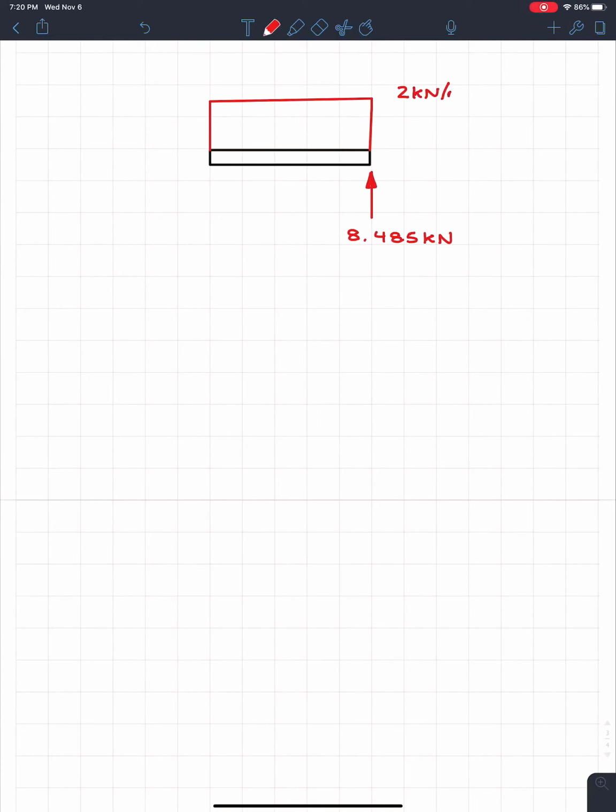That doesn't change. And then, of course, we cut the beam on the left side. So on the left side, we're going to have to replace this with all of our forces. So on the left side, start with the easy ones. Remember, the normal force will always be pointed away. So we're going to have ND. We have a bending moment, and the arrow will always be at the top. So this one will be MD. And finally, we have shear. And shear, if we're analyzing the right side and cut it on the left side, the shear is going to go upwards. That's going to be VD.